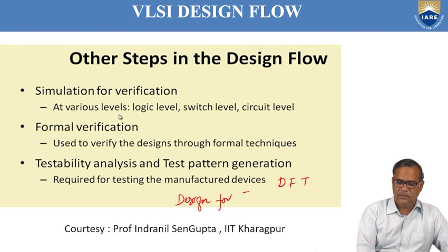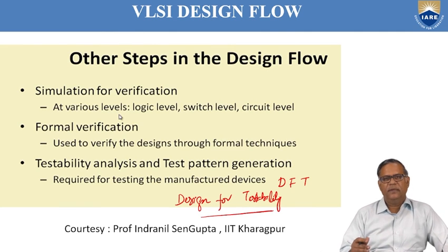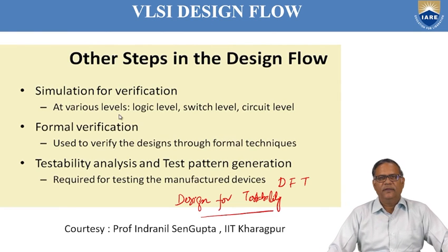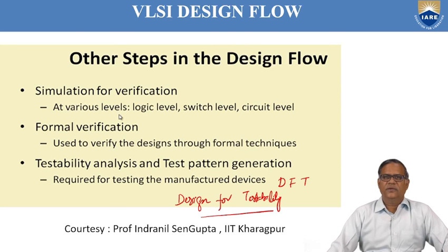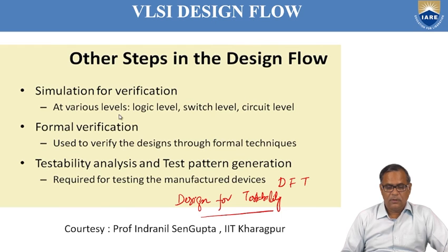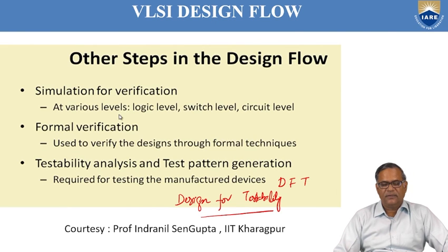That means the chip can be tested by itself by including features like BIST. In BIST, the test pattern is generated inside the chip itself. So these are all the various steps in VLSI design flow.